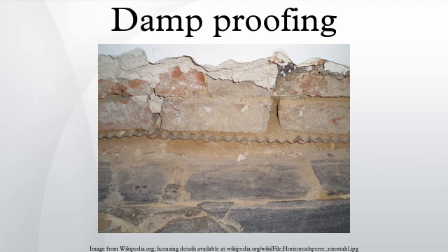The DPC in the inner wall is usually below floor level or, with a solid concrete floor, it is usually found immediately above the floor slab so that it can be linked to the DPM under the floor slab. This enables installation of skirting boards above floor level without fear of puncturing it. Alternatively, instead of fitting separate inner and outer DPCs, it is common in commercial house building to use a one-piece length of rigid plastic which fits neatly across the cavity and slots into both walls. This method requires weep vents to enable rainwater ingress to drain from the cavities, otherwise rising dampness could occur from above the DPC.